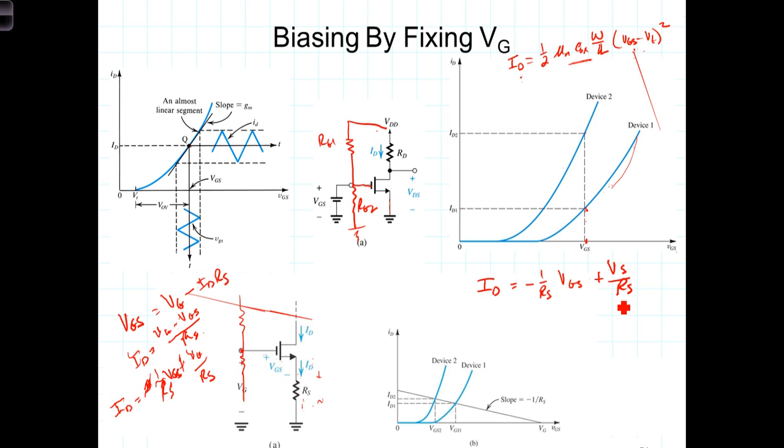Instead of being rigidly controlled, VGS then varies in the opposite direction to I sub d. As I sub d gets bigger, VGS gets smaller, making I sub d get smaller. This equation becomes the equation for what is known as the load line. This equation relating I sub d and VGS draws a new line onto our graph here.